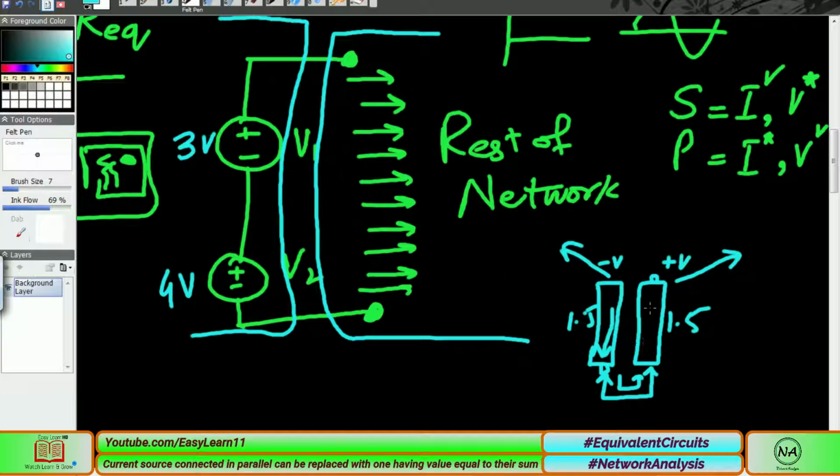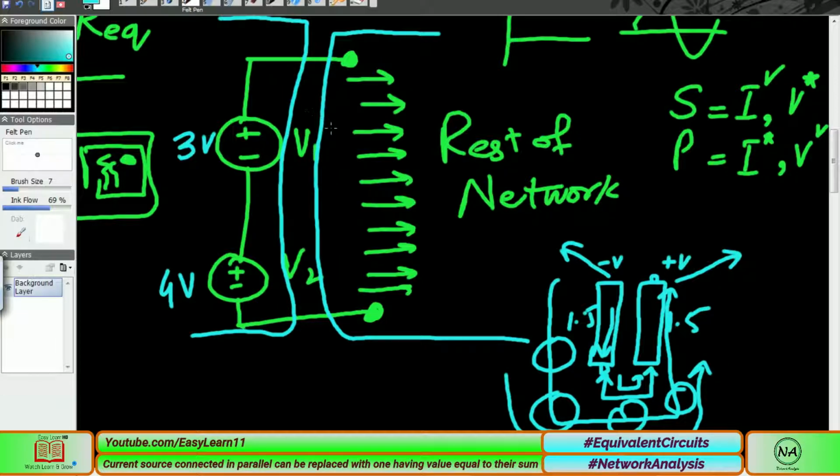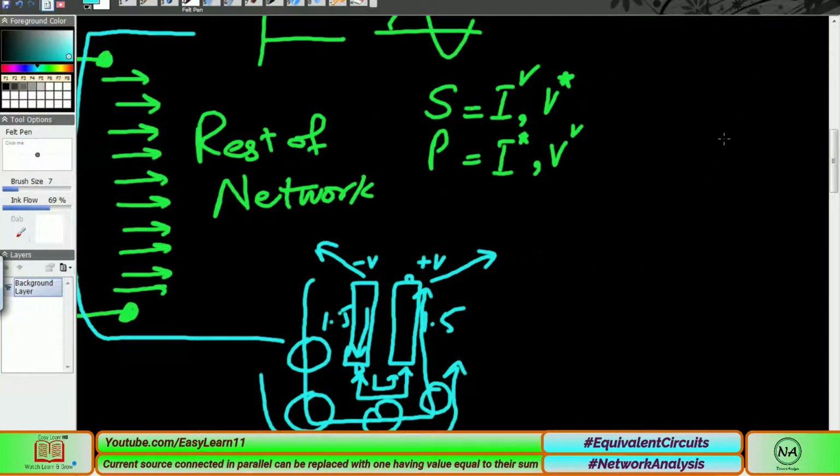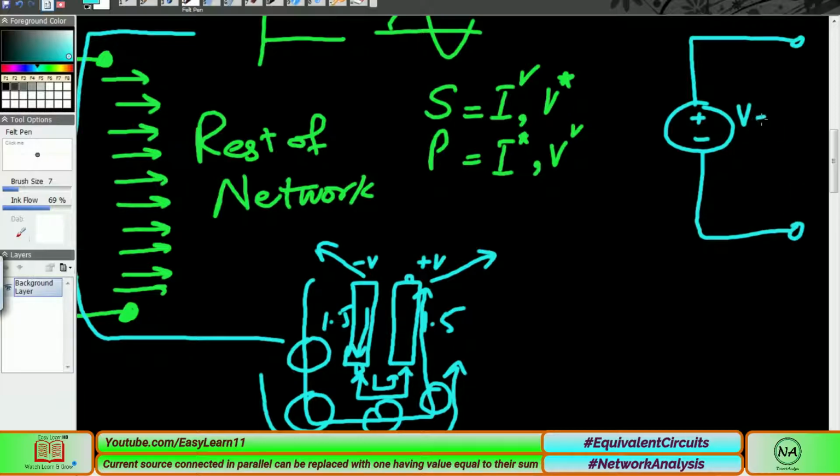So it means that in a series circuit, when the voltages are following throughout the sequence, if the sources are added, they are all going to push this circuit. So we can simply say that the equivalent circuit of this type of network is simple. Just add one simple source, which is the sum of V1 and V2. If there are 3 voltage sources connected, then you can add just 1, 2, 3.